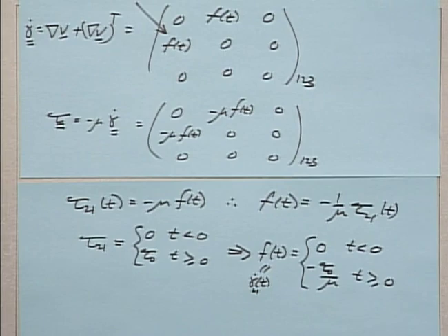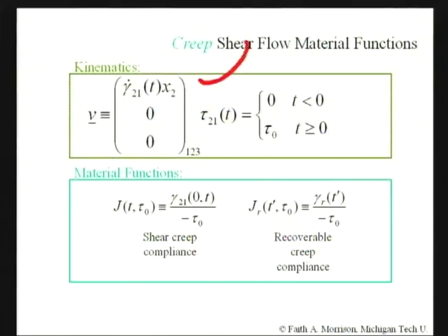We actually didn't want the shear rate, though, because we're going back to the definition of the material functions, and we need the strain. But remember, we calculate the strain from the strain rate. It's the integral of the strain rate between the two limits that are given in the argument. So now that I've got the strain rate, I can integrate it to get the strain.